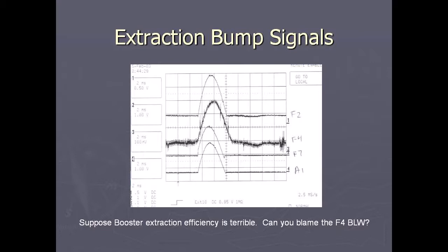So what's the signature of a problem? What would change if I were to encounter a problem? Okay, good. So typical to these guys is a gross amplitude change, right? These guys have resistors in them. The injection pumps used to be worse for this. But there are times when one of these amplitudes will just be way off. There will be a problem with the power supply, and it will fire.